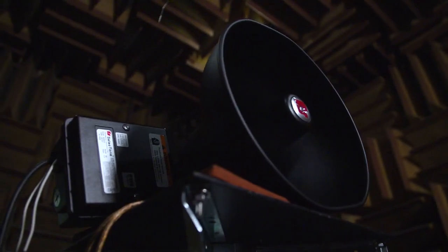maximum. Is there any difference in the dB above the ambient noise level you need to be for tone versus voice? No, but what effectively happens is you can't play voice as loud because it varies in level. Therefore, you can't run the equipment at full volume. Whereas with a tone, it's continuous and you can.